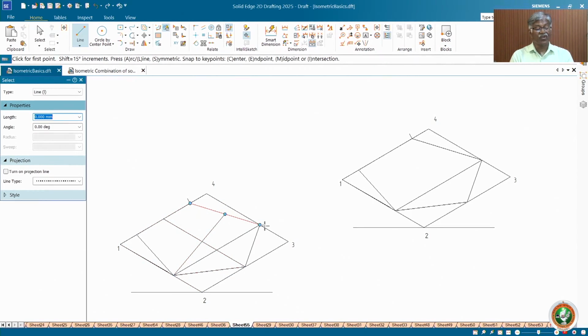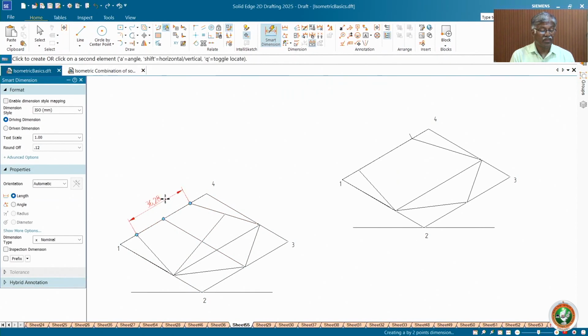Now what you have to do for the frustum is reduce this. For example, the side of the pentagon is some value like 40. After reduction, I have to make it half of the size, say 20 mm or 25, whatever. For convenience, I will take 50% reduction. That is, if this is 40, that becomes 20. Now let me take scaling. You have to go for scale.